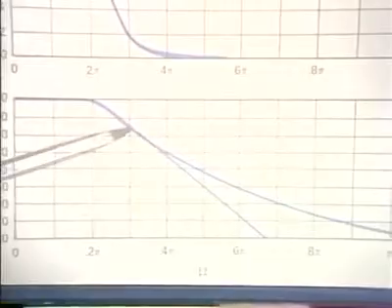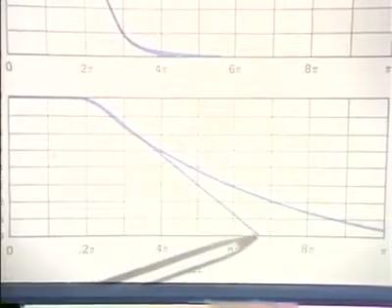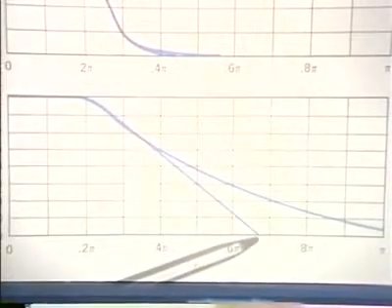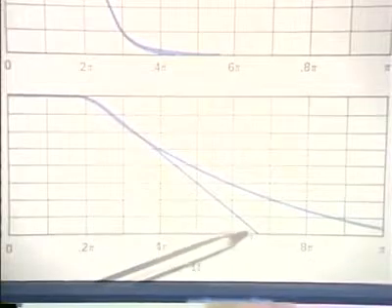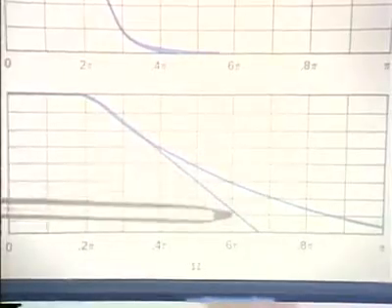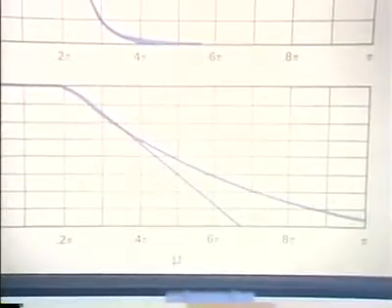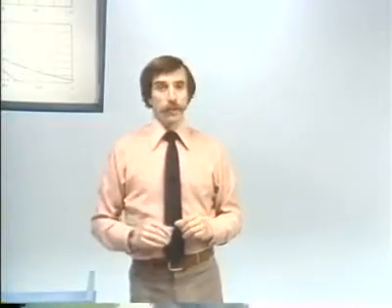And notice, in fact, something very interesting, which is that the filter that we obtained by mapping the Butterworth filter to a digital filter through the bilinear transformation, in fact, falls off in frequency much more rapidly than the one that we got through impulse invariance. A question is why? Now, one thought that might come to mind is, well, impulse invariance has aliasing, the bilinear transformation doesn't have aliasing. That must be a consequence of aliasing. In fact, that's not the reason.